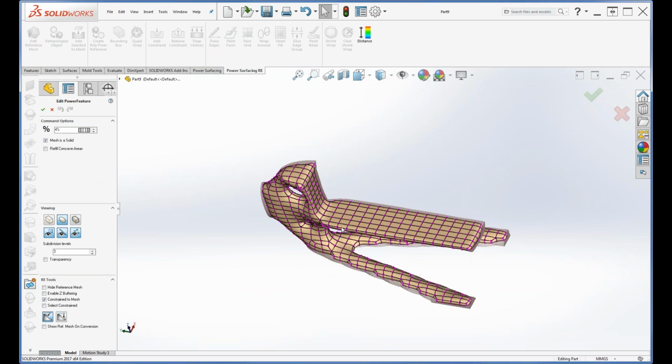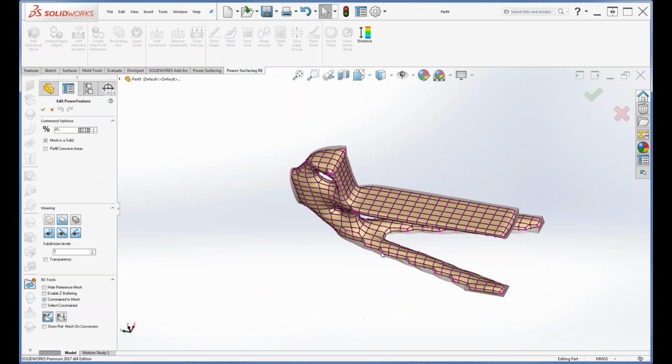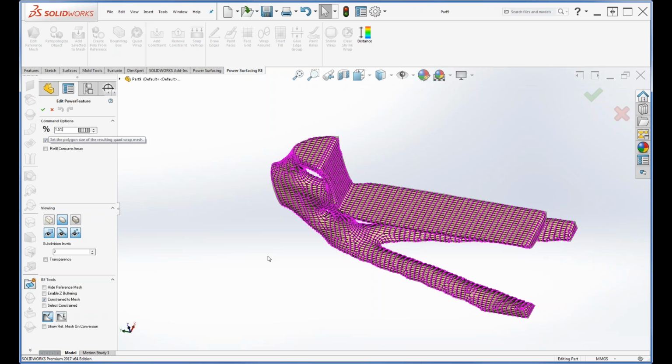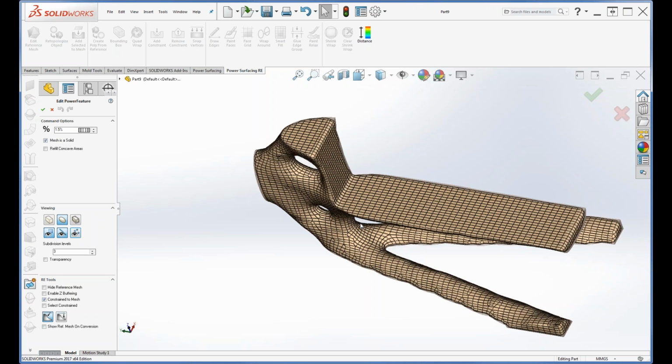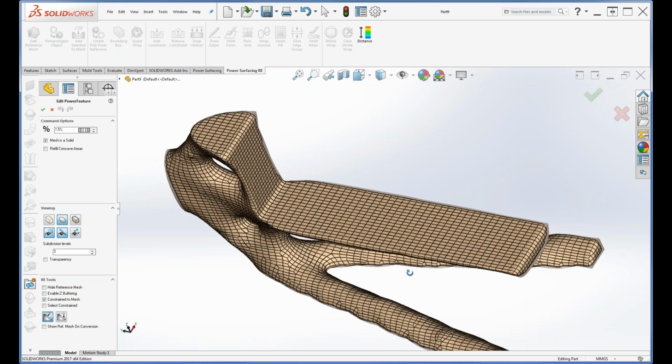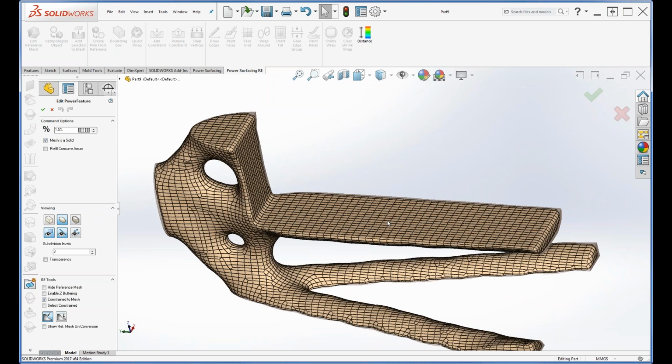And we can decide, well, it's really kind of inside here, so maybe I want a little more accurate than that. And I'm going to go down to 1.5 on this. And there we go. I'll go ahead and turn off the vertices. That'll save us some computation time. And I might look at this, and I really don't know what their point is on this one. I think it's just a model.